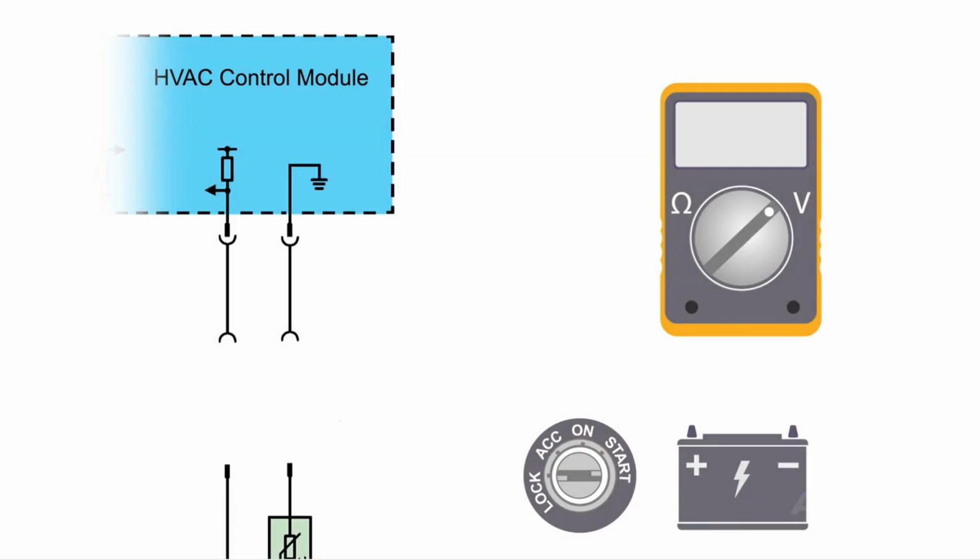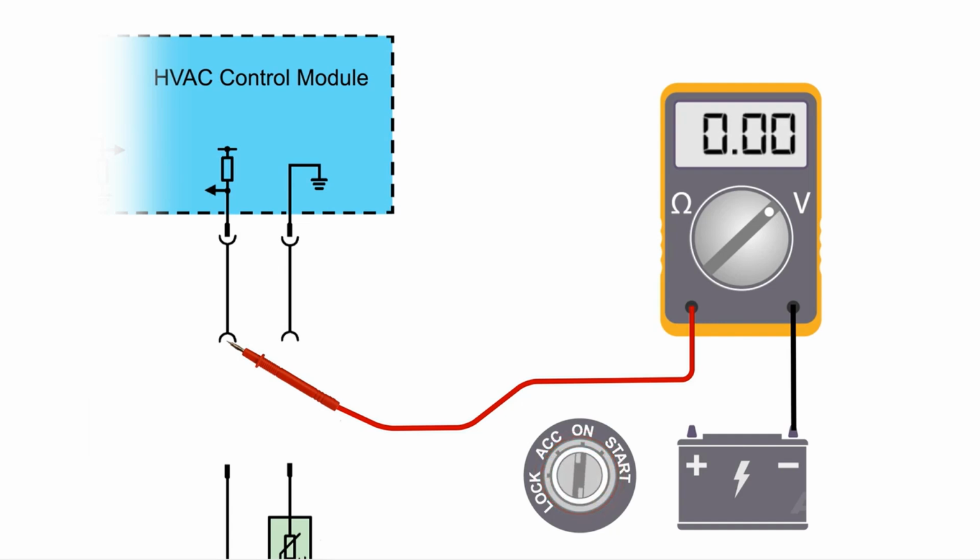Disconnect the thermistor and attach a meter between the battery negative and the signal terminal on the harness side. Turn the ignition on and record the value. You should see 5 volts. Anything over this would be interpreted as a short to voltage. A reading of 0 would indicate a short to ground or open, while anything below 5 volts will indicate excess resistance in the circuit.